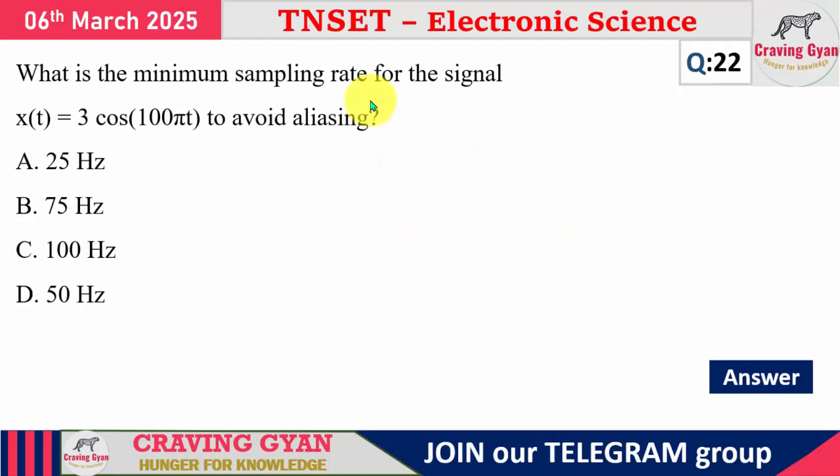What is the minimum sampling rate for the signal x of t equals 3 into cos of 100 pi t? So, I can write it as a cos of omega t. You can rewrite it as a cos of 2 pi f t, which will be equal to, what is the value of a?